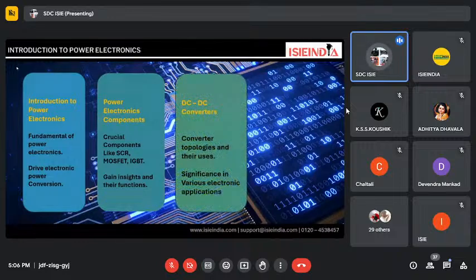Along with that, we come to the DC to DC converter. In electric vehicles, we use DC to DC converters as per the power requirement of the auxiliary components, as well as the power required for each of the components. Take the controller: it has a lot of functions and features, and a lot of wires. Some wires deliver power to the motor, some to the key switch, and some to the Hall effect sensor and throttle connection, and they have different voltage ranges. For example, we give 48 to 72 volt for a two-wheeler BLDC motor.